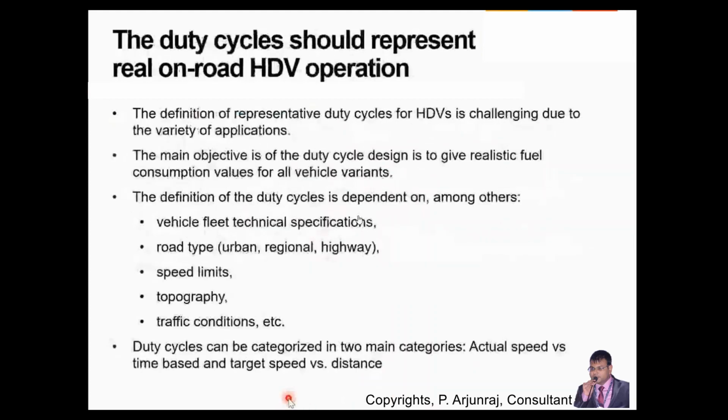That's why even when you do some of the trials like city durability test or gross highway durability test or accelerated durability test or rough road durability test or composite durability test, whatever you do, you have some target, right? Whatever is the target speed, and you also have some of the kilometers being fixed for that as well. That's where the distance comes into the picture.